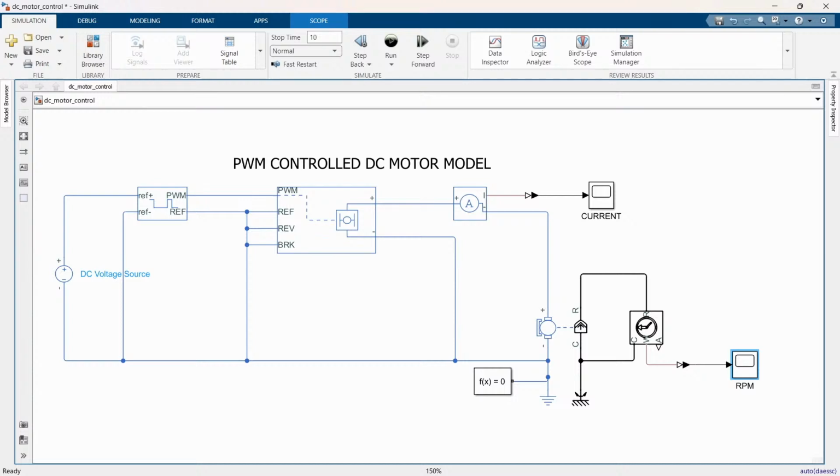So this is the impact of the duty cycle of this PWM signal, because this PWM signal determines the average voltage applied to the motor. A higher duty cycle leads to a higher average current drawn by the motor to maintain the desired speed against that load. So based on the duty cycle, when the duty cycle is increased, resulting in a higher average voltage, the motor speed tends to increase. Conversely, if you decrease the duty cycle, it lowers the speed. So this is the way you are going to control the speed of your DC motor in your electric vehicle.